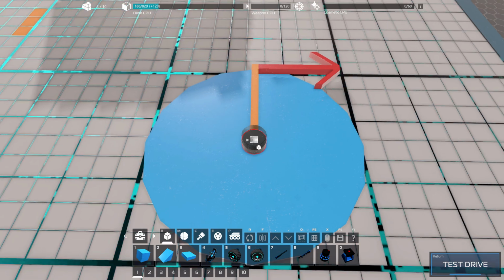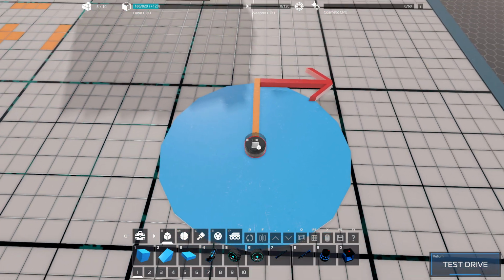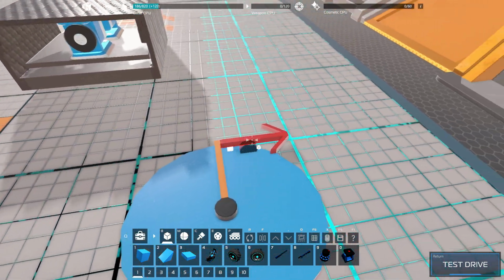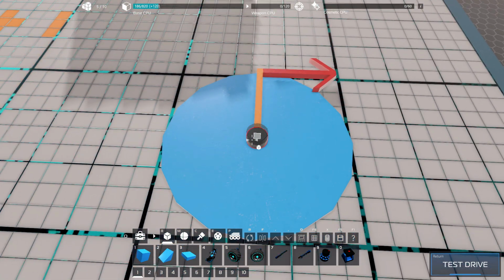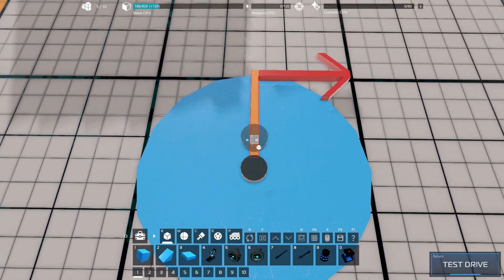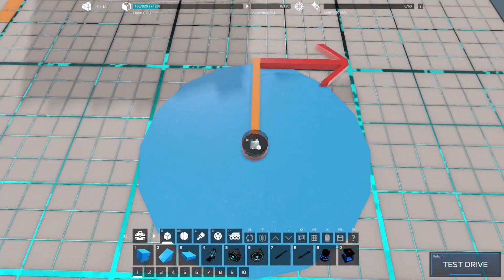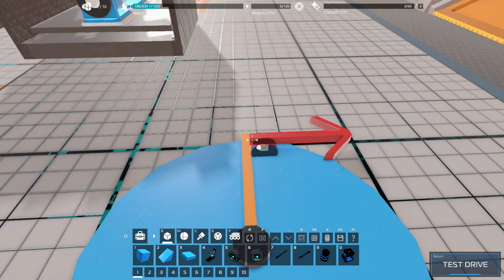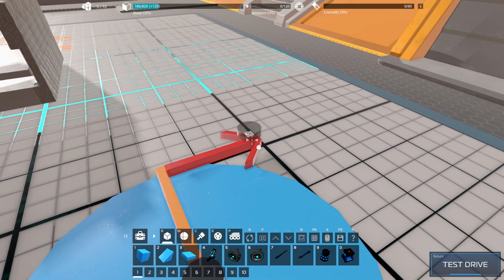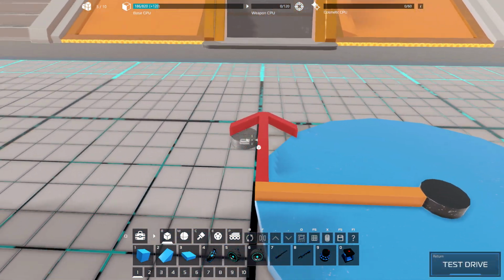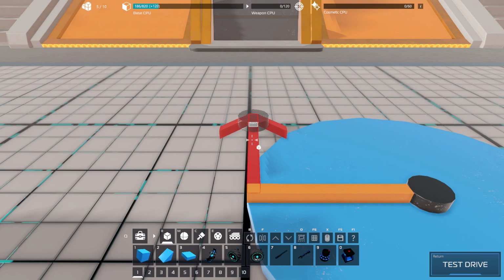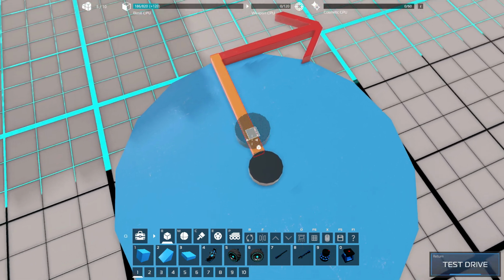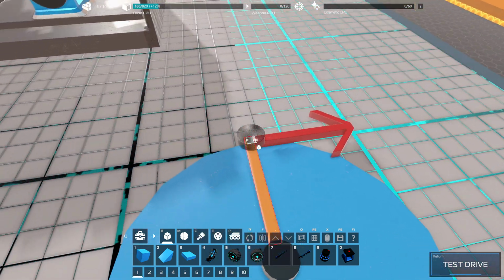So your moment at any point is equal to the distance from the point of rotation, and that could be your center of mass, which can be a function of where your forces are applied, or it could be a fixed point, right? A hinge or a rotational pin joint. So your moment around a point is equal to the distance times the amplitude of the force acting perpendicular to the vector coming out from your center point. So basically this length times the force equals your moment, right?